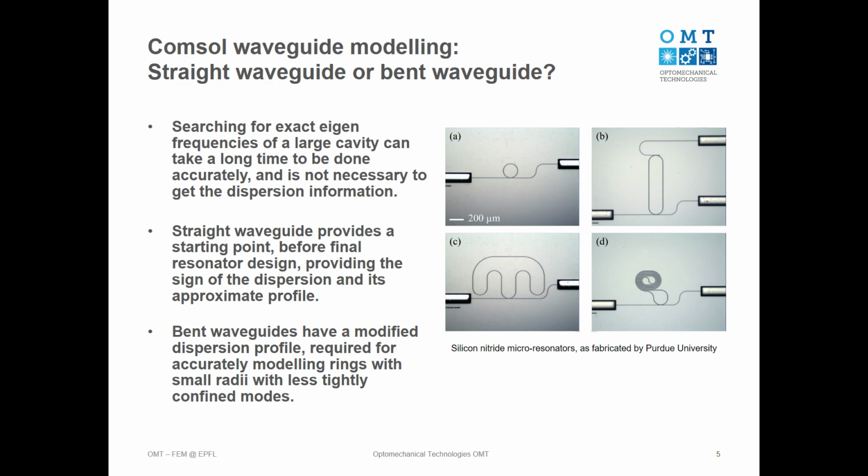So it's good to start with simply calculating the per meter dispersion of a straight waveguide, and then, once you decide on your resonator architecture, go for a full bent waveguide dispersion calculation with Comsol.